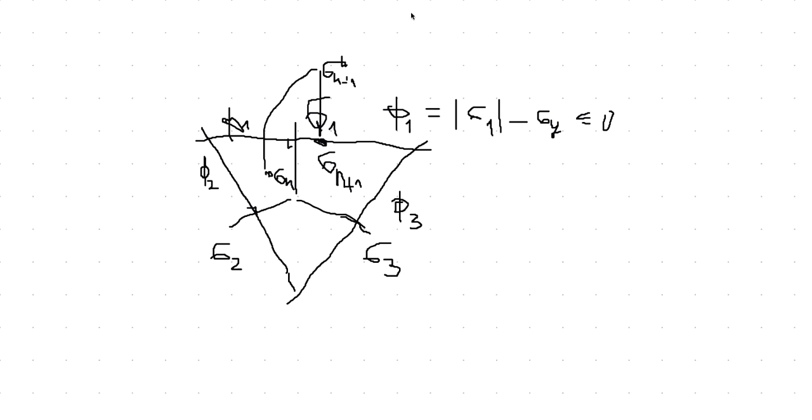Another scenario would have been if I jumped up here, and this was my sigma n plus 1 trial. Then in this situation, most likely, I'm going to get here, and I have to get the normal vector from that surface and the normal vector from that one, to get my corresponding contributions of gamma plastic 1 and gamma plastic 2.